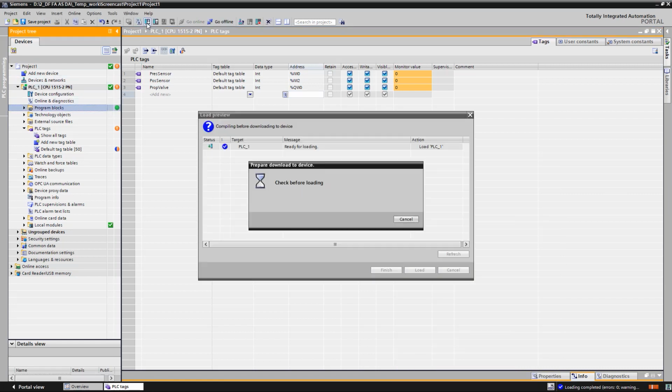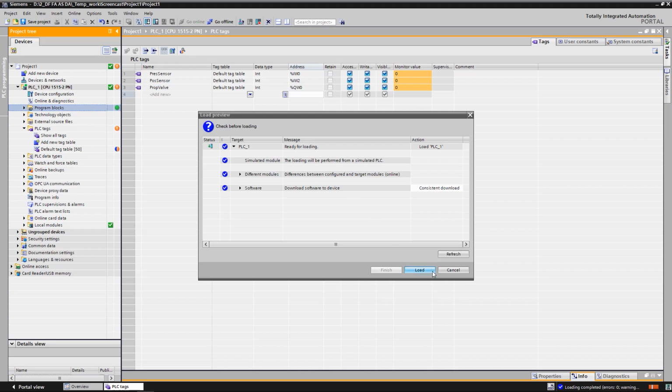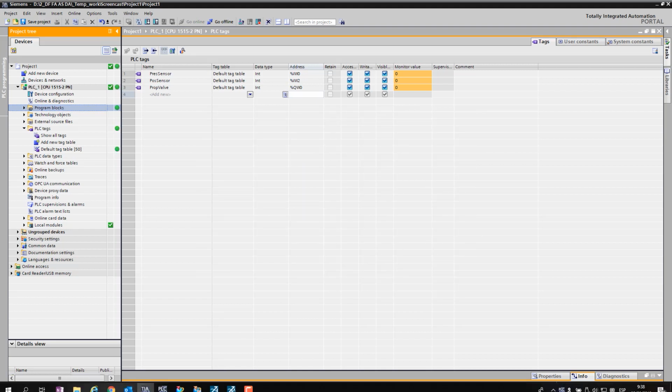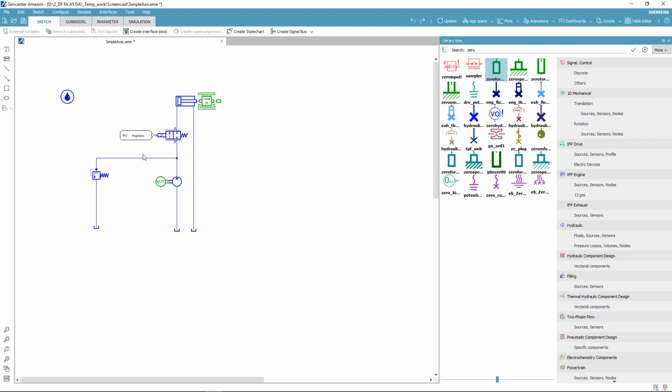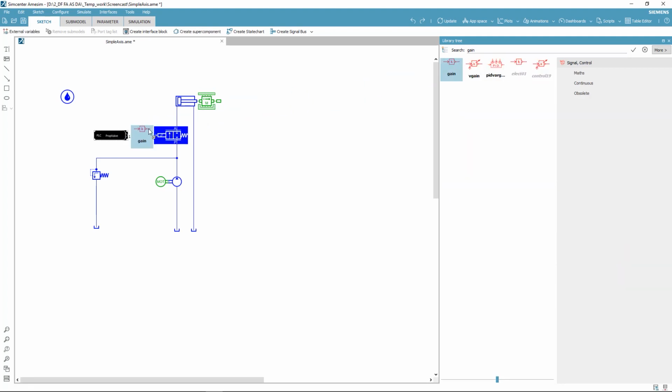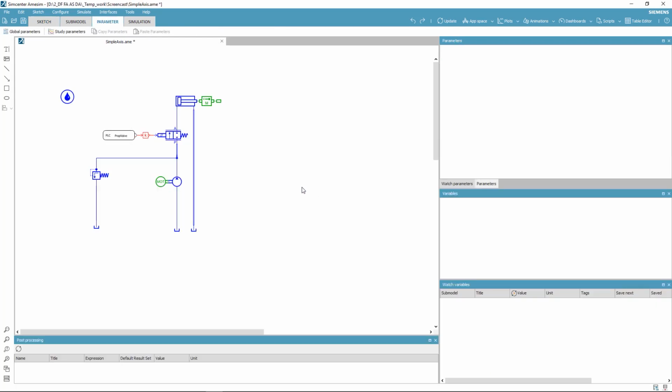27,648. We will now download the PLC code to PLCSIM Advanced, our virtual controller for the S7-1500. Since the value that comes from the PLC is a raw automation value between 0 and 27,648, we need to add a rescaling for 10 volt.